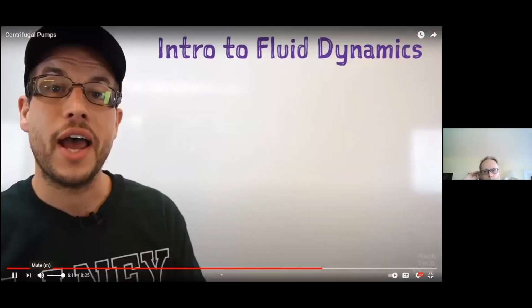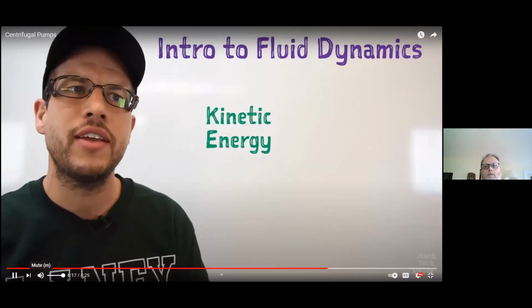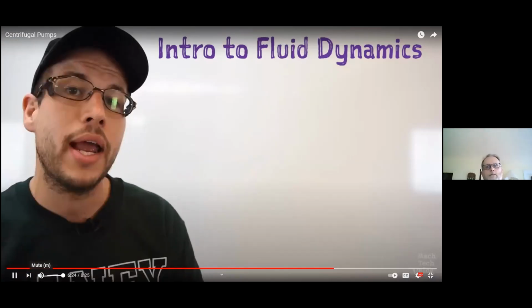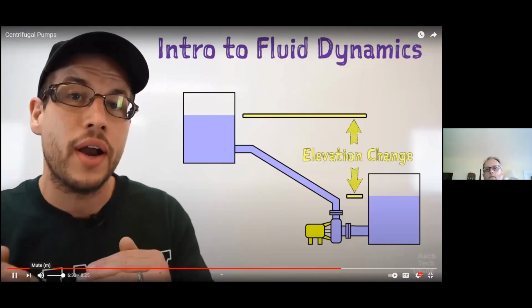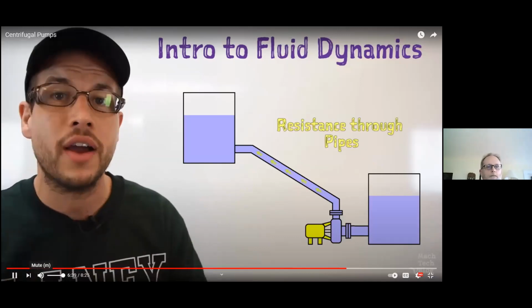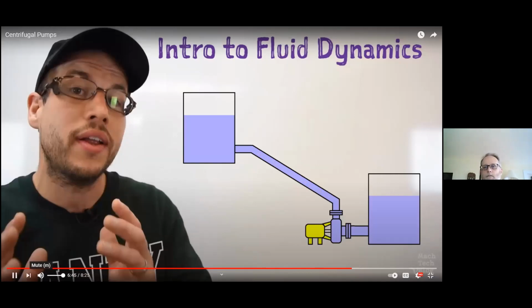Now, the increasing area of the volute chamber is essential to the function of the pump because that's how the pump develops pressure. We've talked about how the impeller imparts kinetic energy to the pumped fluid. And when I say kinetic energy, think of it as the speed of the fluid flowing through the pump. But flow speed is only half the equation. A pump also needs to be able to develop sufficient pressure to meet the requirements of the system. Usually this involves overcoming gravity by raising fluid from a lower elevation to a higher elevation and overcoming the resistance or friction of the pipes which conduct the fluid. Think of pressure as the ability to accomplish a task, and flow speed as how quickly the task can be accomplished.